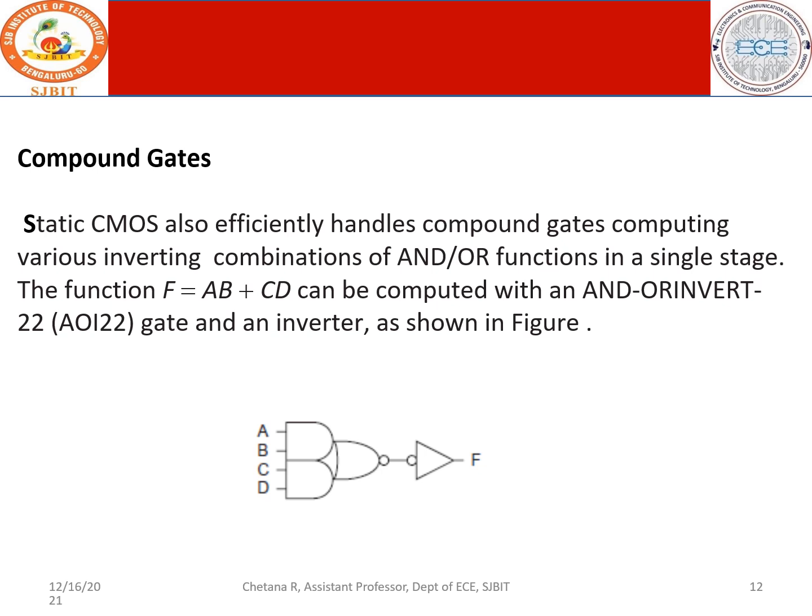So what do you get? You have one AND gate which is AB, you have another AND gate which is CD, and the whole of these two inputs, AB plus CD bar, is got at the output of this. To overcome the complement, you have to again bubble push in front of the inverter, and you get your final output F, which is equal to AB plus CD. So you had this NOR representation as bar, the bar is removed, and finally you get F equal to AB plus CD.